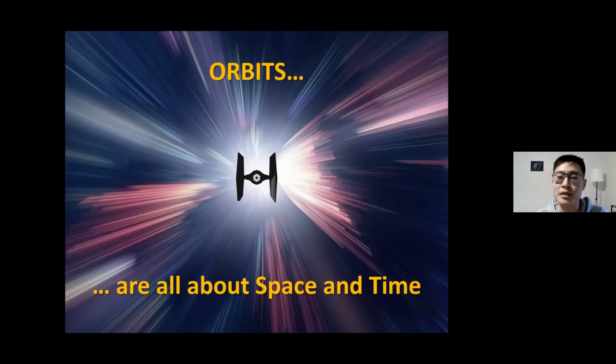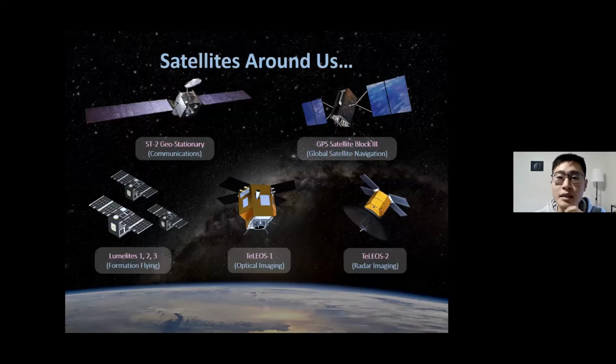And so because of that, that also constrains the time that it takes for you to revolve around the planet. So Kepler's law says that your period is proportional to the power of 3 over 2 of your orbital radius for a circular orbit. And so a lot of these orbit designs, you have to consider not just the space, but the time. How often do you want to revisit a particular location, and so on and so forth. So it's just to prime the way we think a little bit about space mission design. It's a 4D problem, right?